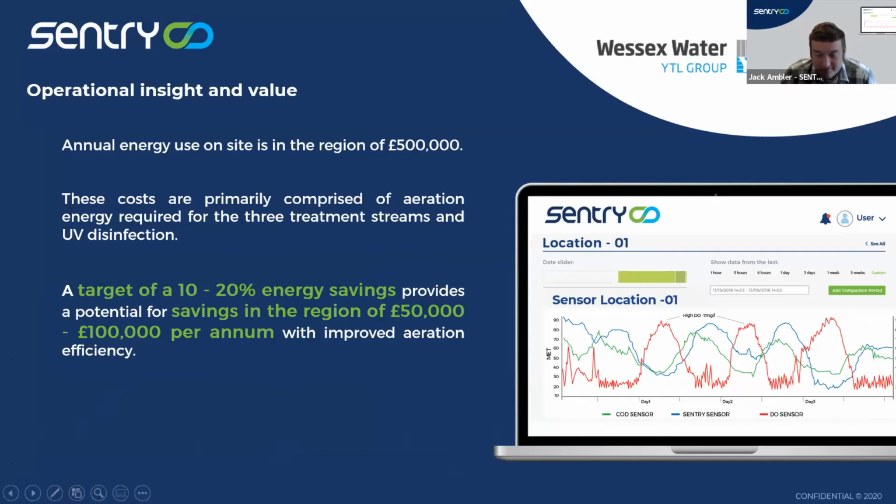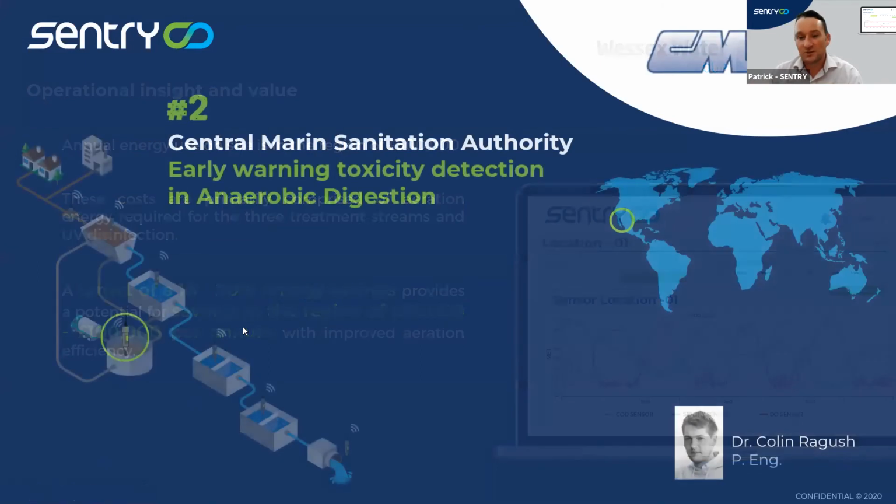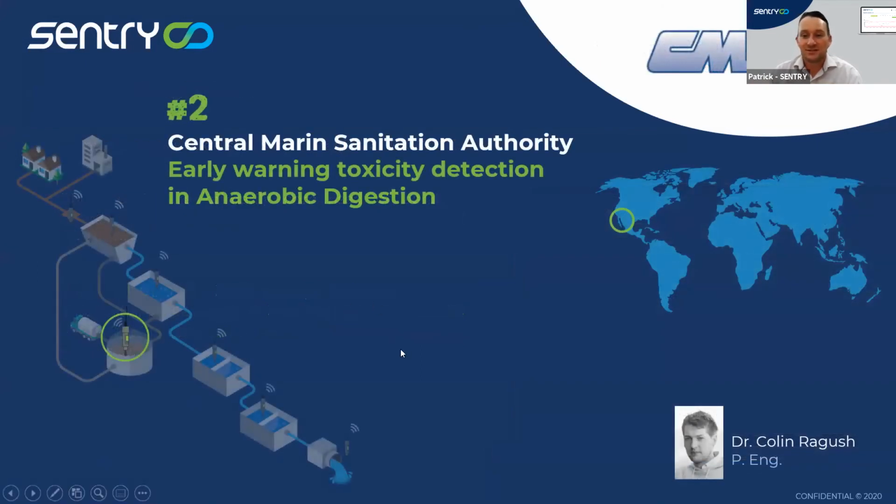Fantastic. Thank you, Jack. Okay. So Wessex is fantastic. So that's one for the aeration optimization people. And then again, looking at that providing that feed forward signal from a location before the aeration basins and being able to inform or help the DO get to its set points more accurately, and maybe providing that early warning for those load changes.